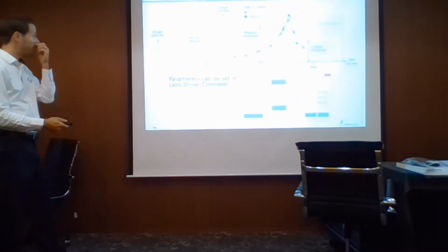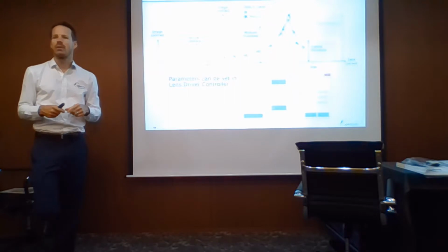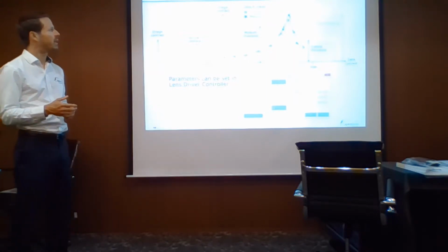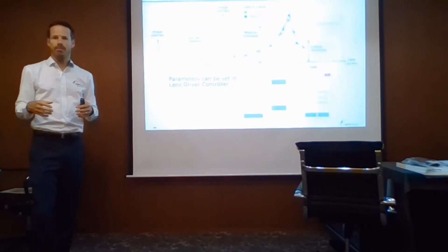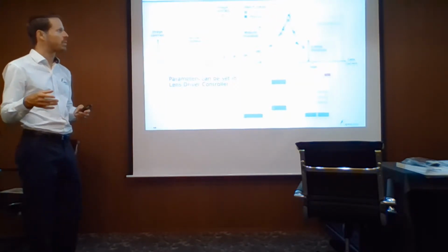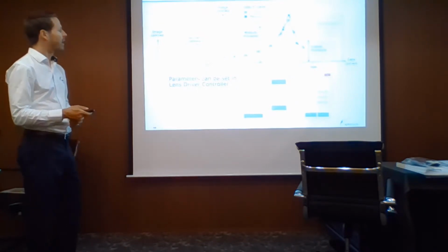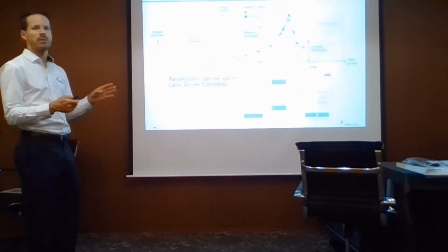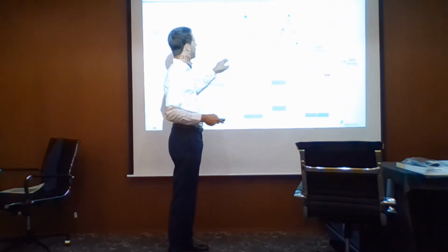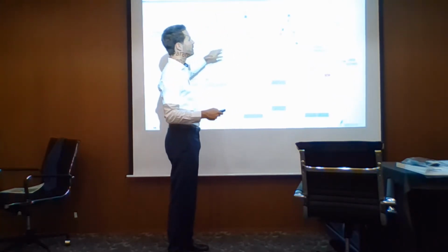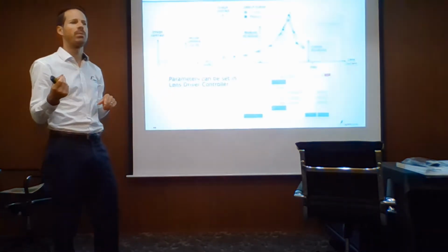There's an autofocus implementation in our own software. We've used the IDS SDK to include the UI viewer, so if anybody wants to use IDS cameras with our software, this works quite nicely. We can then also do that again on the demo. We've implemented the autofocus with 3 steps. First step, you increase the current, and the contrast value is read out of the image. We use a Sobel filter to get the contrast number.